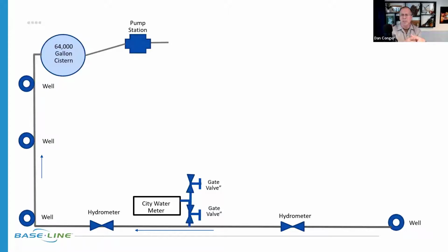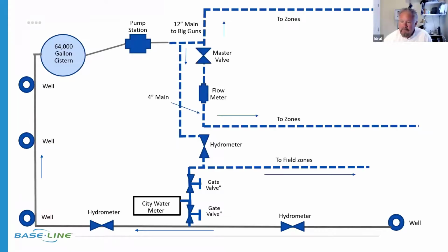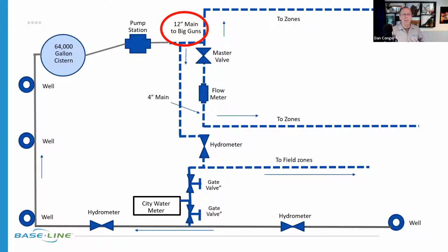And the pump station, pretty high flow on that one, 1,200, 1,500 GPM, if I remember. Right. It's got the capacity for up to 1,500 gallons. It's got to be able to handle several of those big guns. But at the same time, it also handles the smaller turf and scrub and even some drip zones. So when we bring in those main lines, here are those main lines we're talking about. We've got multiple main lines out here, but it's those big rotors that are the crux.